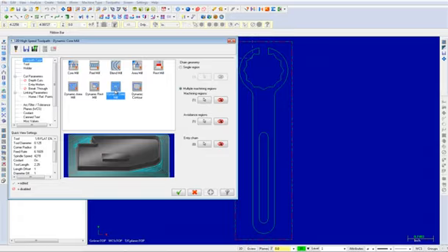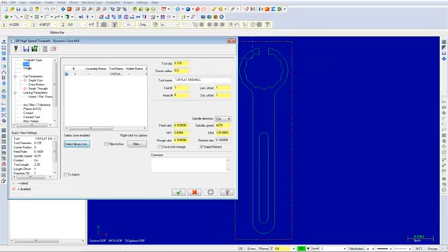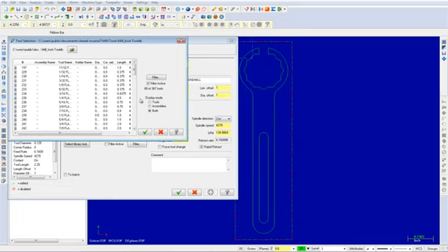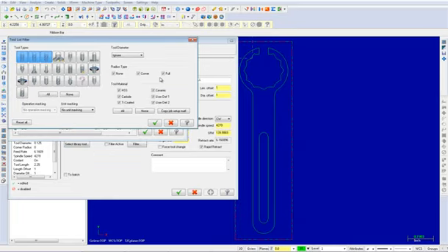We will now choose a 1/4 inch flat end mill from the library and set the tool parameters. To do this, select Tool from the Tree View list. From here, choose the Select Library Tool button and then the Filter button. Select the None button and then under Tool Types, choose the flat end mill icon. Under Tool Diameter, pick Equal and input a value of 0.25 as shown. Once complete, select the OK button to exit the Tool List filter.